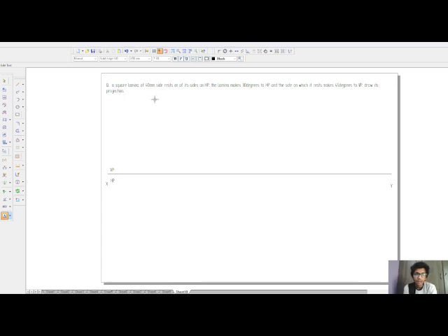Also, we should determine the resting edge or the resting corner of the given lamina. Here, the resting condition is that the surface is resting on HP with one of its sides. Since the resting condition of a square is on its sides, the left side will be a side of 40 mm. Using a visible line, we will draw a square of 40 mm side.